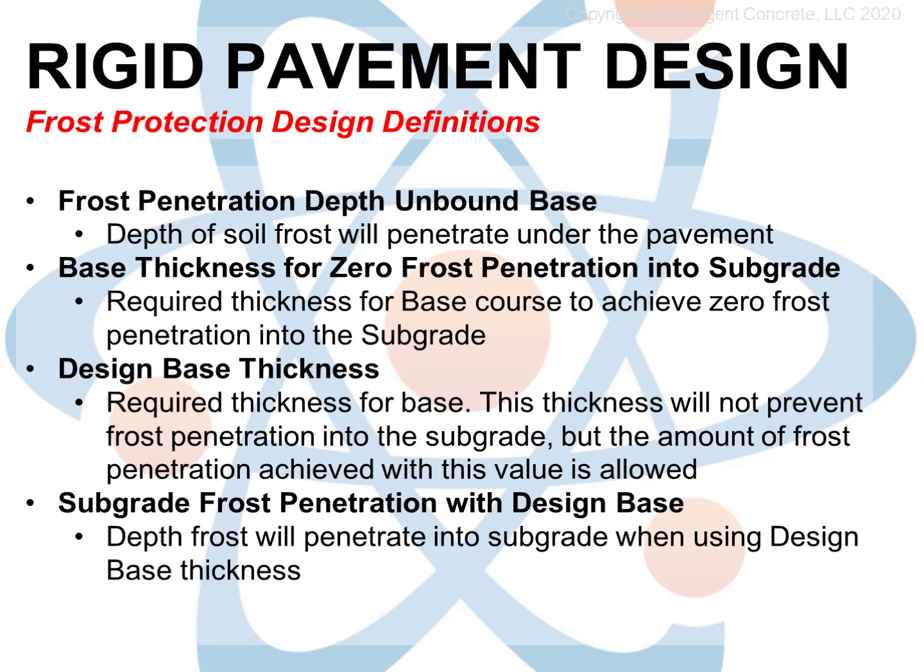Here are some frost protection design definitions. Frost penetration is how far into the soil frost is anticipated to penetrate under the design freezing index conditions. Oddly enough, loosely compacted soil undergoes far less frost penetration than dense soil because the air in the void spaces tends to act as insulation. Loose soil that would be completely unacceptable for direct placement of pavement might undergo only half the depth of frost penetration as highly compacted, low void ratio soil.